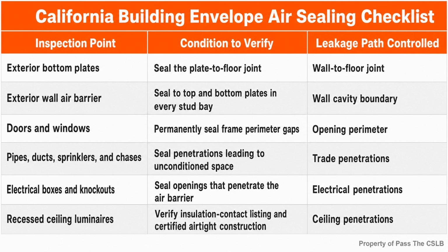I picture the enclosure as a 6-sided box. It has 4 sides, a top, and a bottom. Then I picture every plumber, electrician, heating and cooling installer, sprinkler installer, and low-voltage technician arriving with a reason to cut through that box. Those penetrations are necessary. Leaving the box open around them is not. The useful memory connection is this: find the boundary, follow every hole, and seal before concealment. That short sequence captures the general B responsibility better than memorizing a random collection of caulk locations.